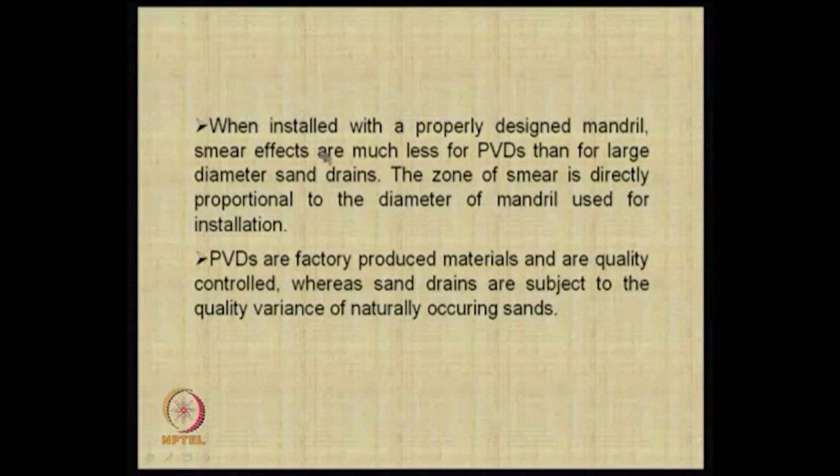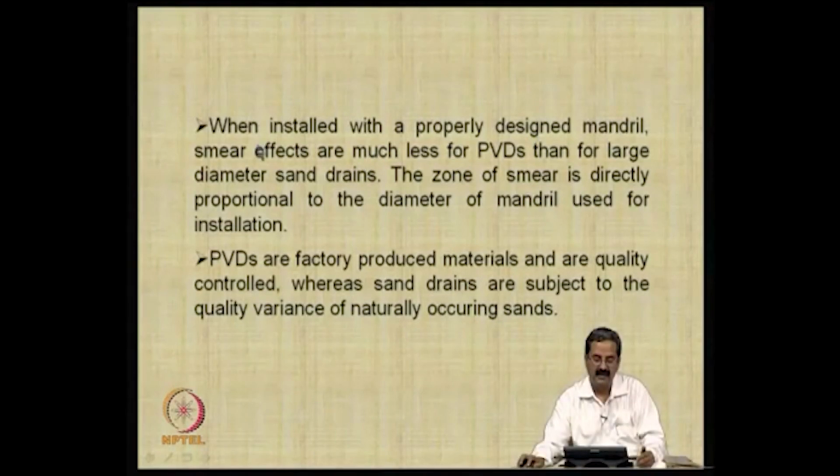So, when installed with a properly designed mandrel, smear effects are much less for PVDs than for large diameter sand drains. As I just mentioned, the sand drains have smear effects. So, the zone of smear is directly proportional to the diameter of the mandrel used for installation.